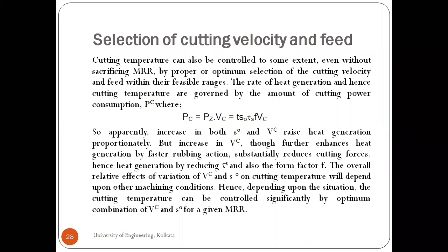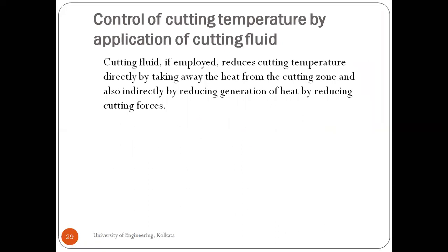You cannot just draw a straight conclusion that these are the directly proportional factors which will generate the cutting temperature. There are many things which you have to consider. You have to perform some experiments to check what exactly is happening. And definitely this equation is a very important equation, and you will get direct relations with the cutting speed and the feed for a certain value of the material removal rate.